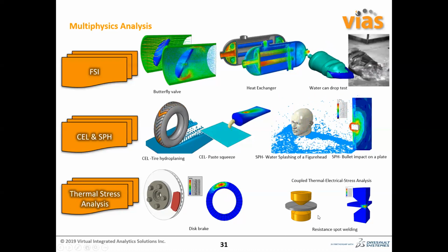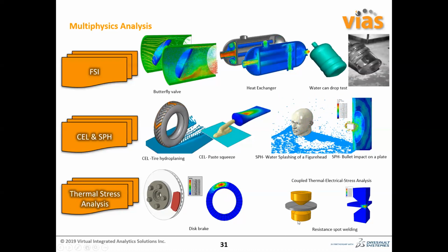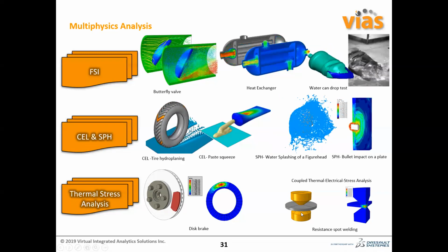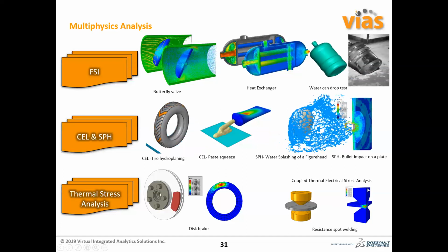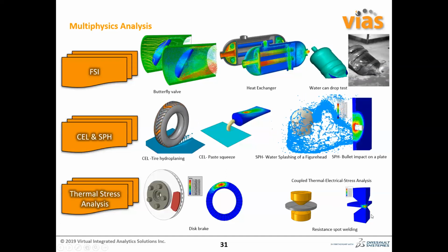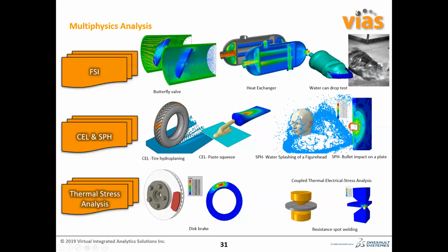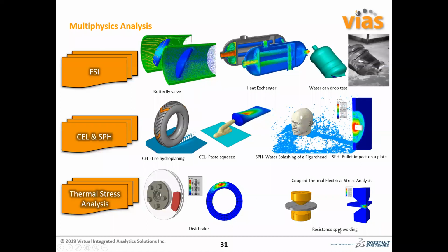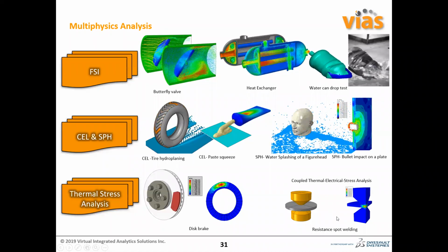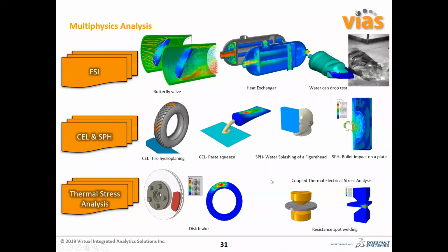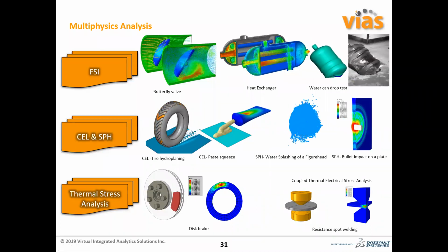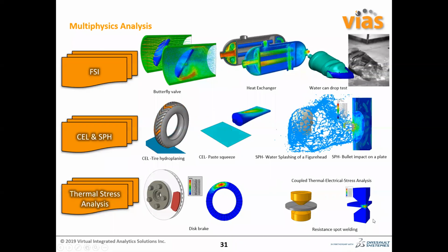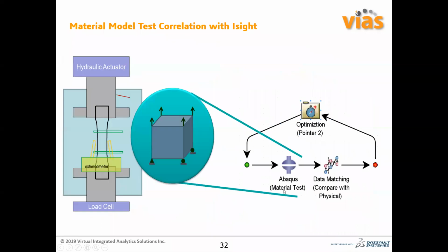And even in certain scenarios, like when you are passing current in the spot welding scenario, you are passing a current through the sheet metal, and because of the contact pressure, the electrical flow and the resistance, there will be heat generation, and the sheet metal will be fused together at that location. This kind of resistance spot welding scenario is very difficult to simulate with SolidWorks simulation, where Abaqus can really come in handy, and it can define better parameters for getting a better simulation strategy.